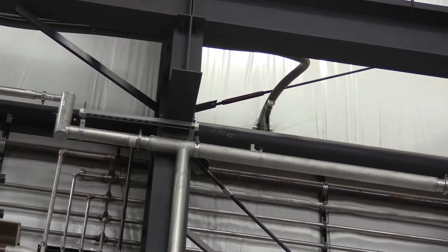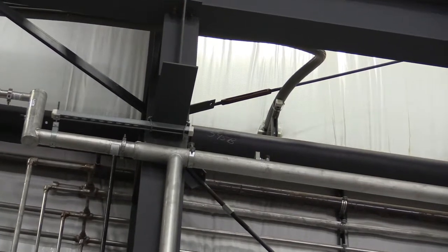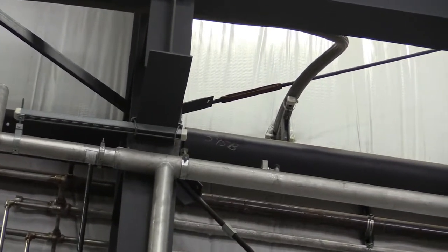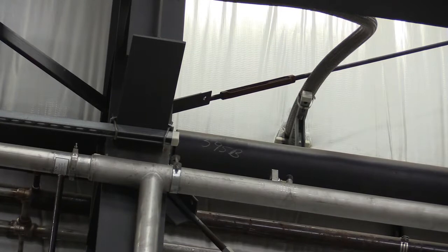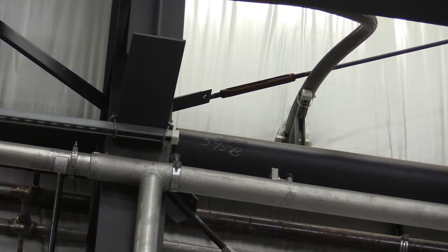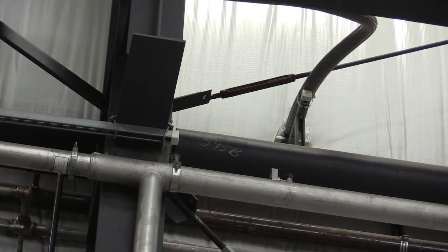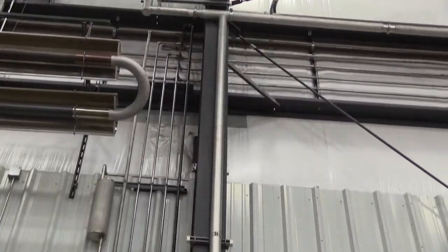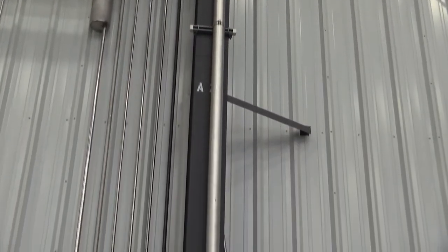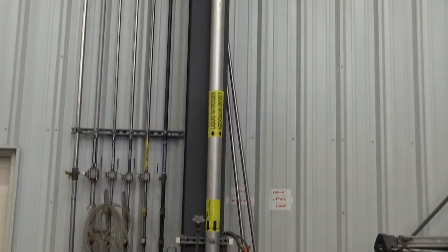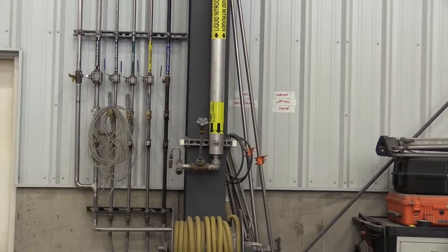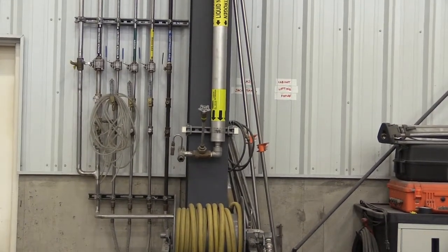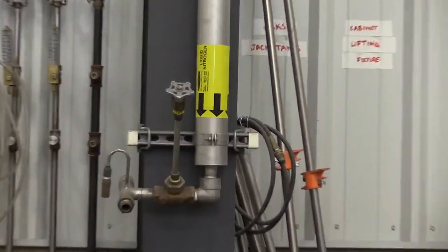One is to use a cryo vent exhaust heater. This heats the exhausting gas to keep the exhaust frost-free. This should not be used in confined spaces. The second option is to run the exhaust outside using VJ Flex. On drops near the use points, without vacuum jacketed valves, internal traps can be used to stop frosting of non-VJ valves during non-use times.